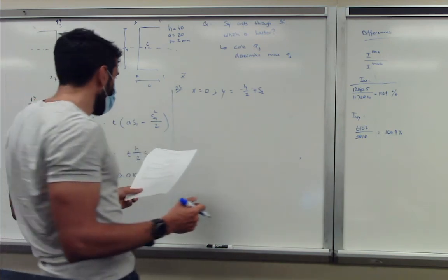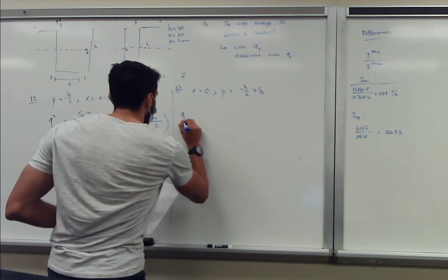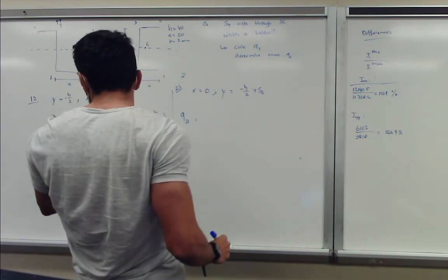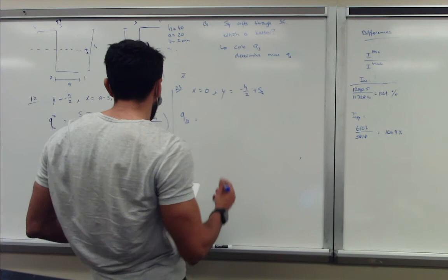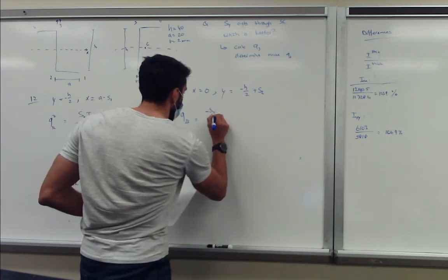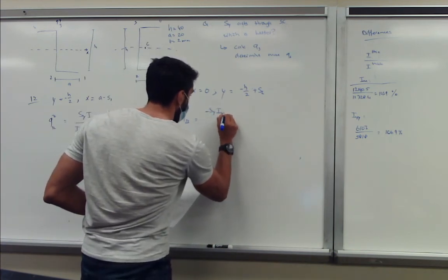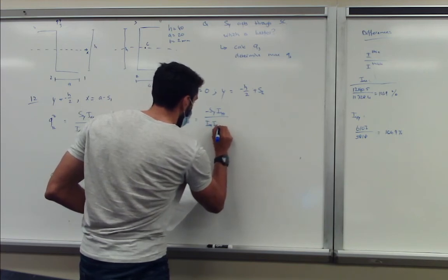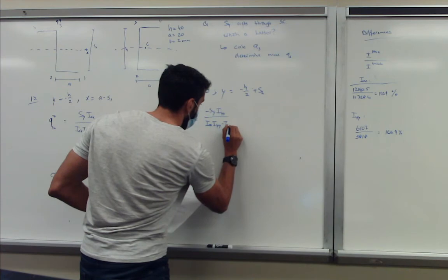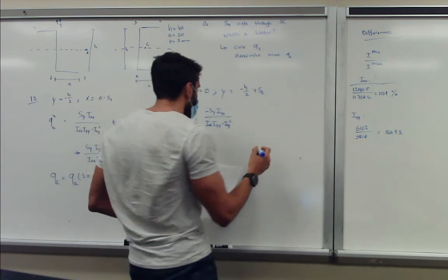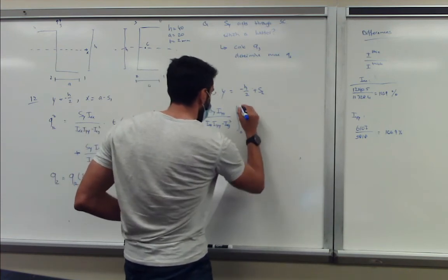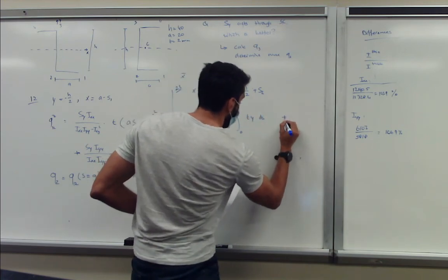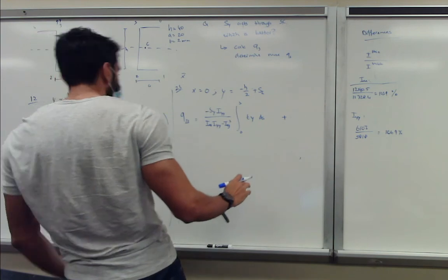So again, for Q2,3, this part was the integral of t x ds, so that one drops. So you get minus Sy over Ixx Iyy minus Ixy squared, and then the integral from 0 to s of t y ds, and you cannot forget to add Q2 to it.